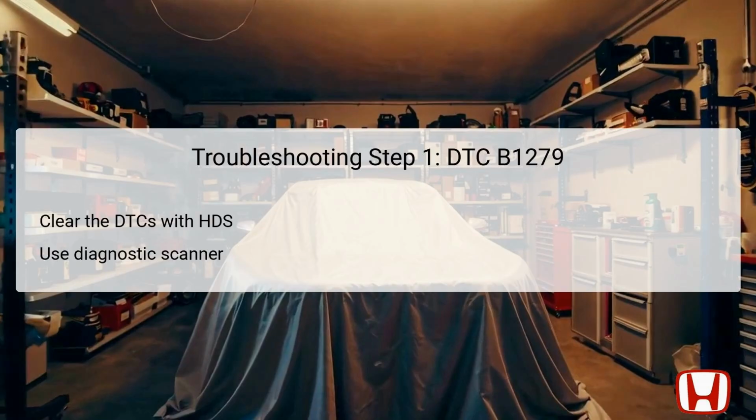The first step in troubleshooting DTC B1279 involves using the HDS, or Honda Diagnostic System, to clear any existing diagnostic trouble codes. This is essential as it resets the control module's stored fault entries, allowing the technician to determine if the fault is persistent or intermittent.